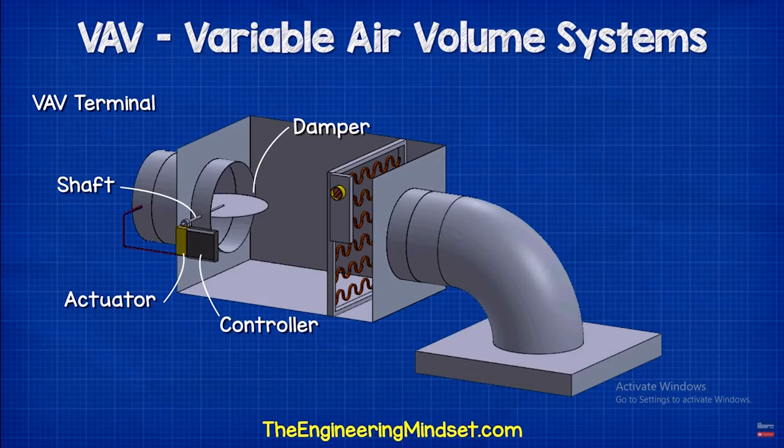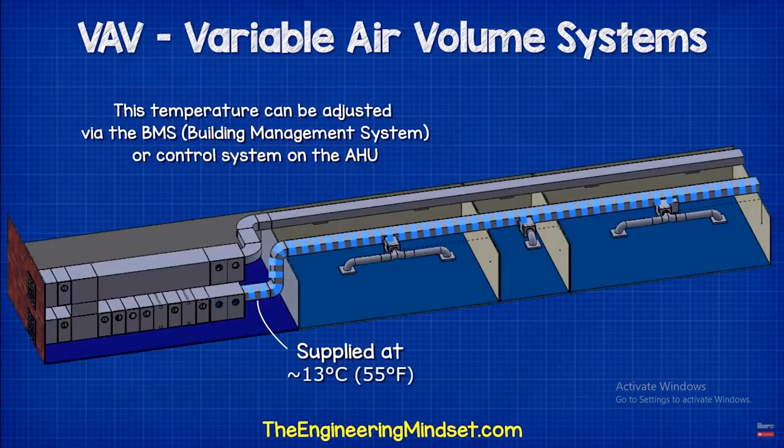You don't necessarily have to have the reheater inside, but it's fairly common, especially in colder climates such as Europe and North America. The reheater battery doesn't necessarily have to be electric. It could also be fed from the hot water system or even a heat pump. But electrical heaters are most common because they are very simple to install in a duct.